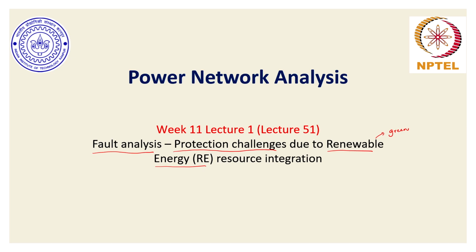So to limit the discussion, I'll be expanding on three bullet points. I'll be emphasizing the impact of renewable energy resource integration on short circuit capacity evaluation, also sometimes known as short circuit ratio, and the impact that this integration will have on the SCC or SCR of the overall network will create difficulty in finding the relay or the circuit breaker settings.